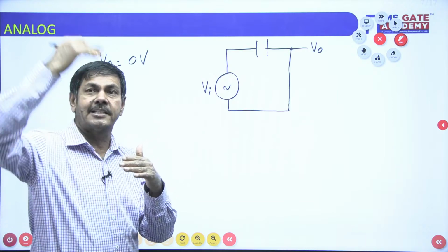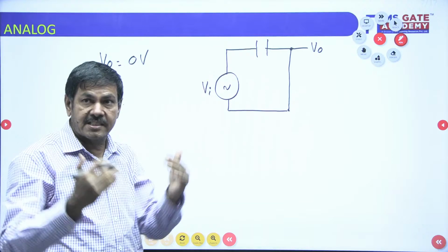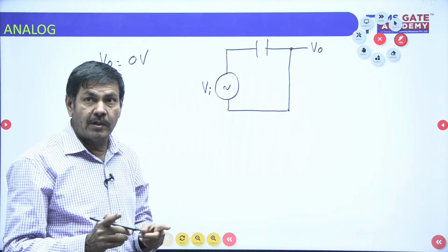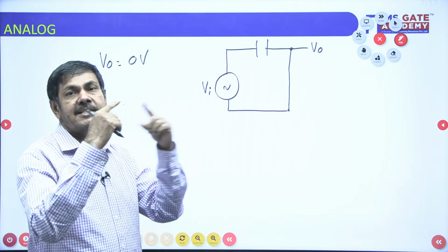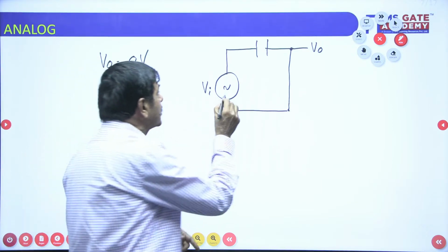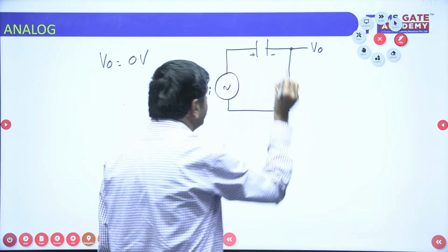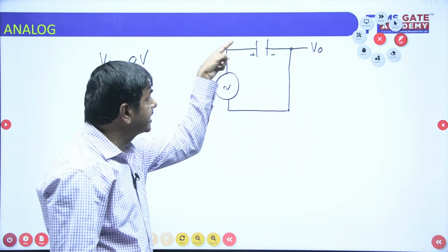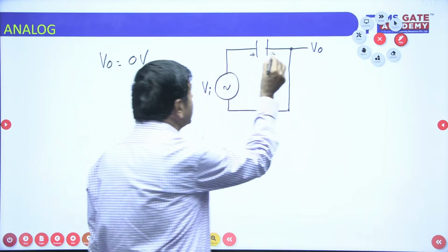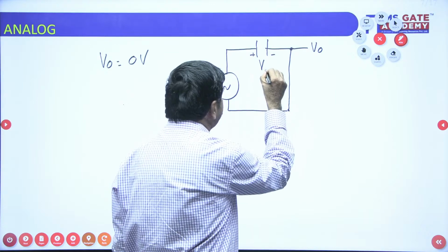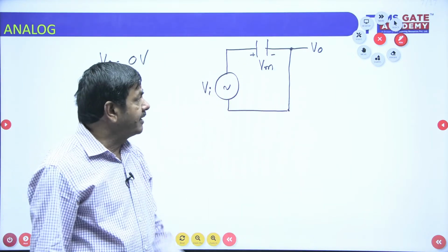And finally it reaches the maximum voltage only. When the capacitor starts charging, meaning when the diode is forward biased, the charging of the capacitor is done. So here it slowly rises with a polarity of plus and minus, positively increasing. The voltage across this capacitor is to be taken as Vm. The maximum voltage is going to be formed here now.